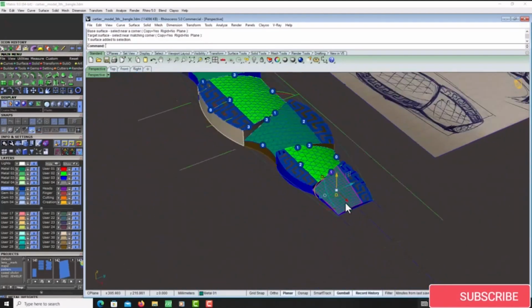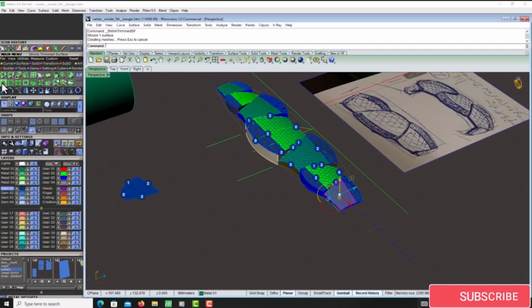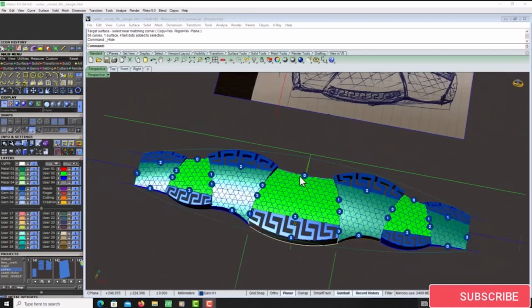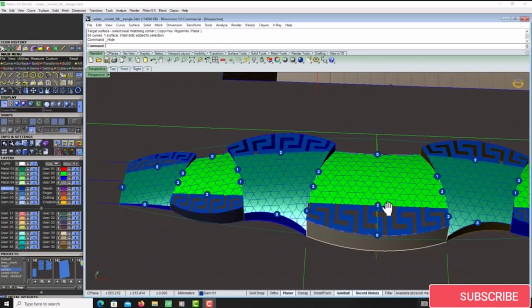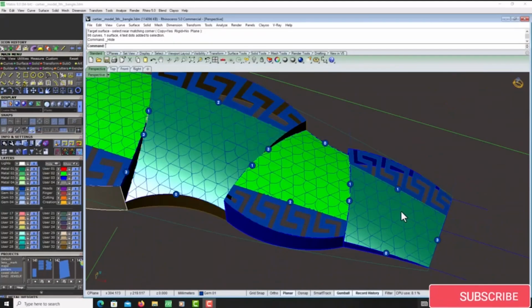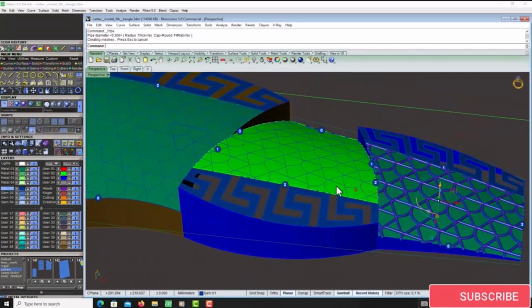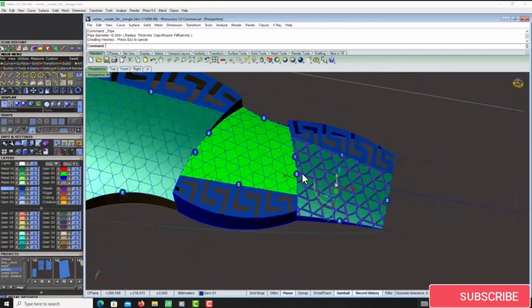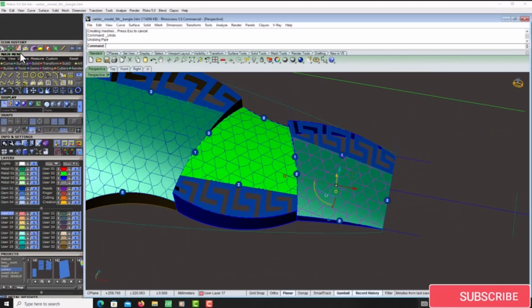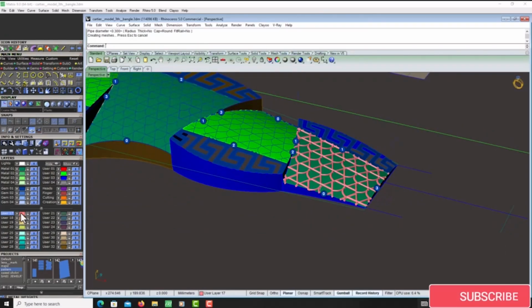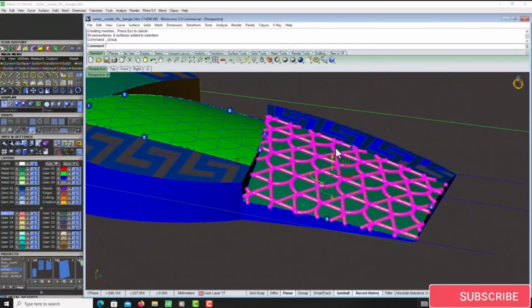Then you flow along the surface, go to transform, click on your projected pattern, enter, base, enter, and click on a green surface, and then enter. Green surface means target, smashed surface is base surface, and your pattern is your curves. Then you finish the projecting patterns or flow along surface patterns.